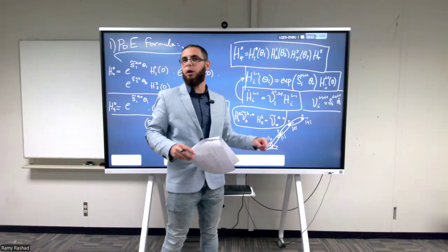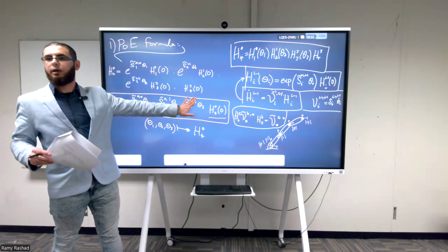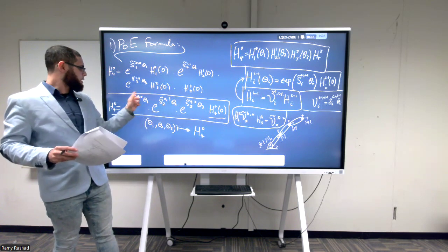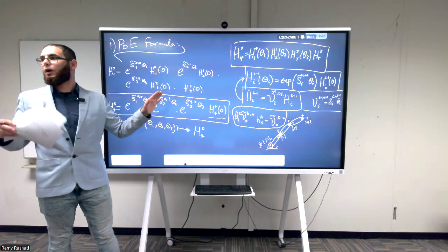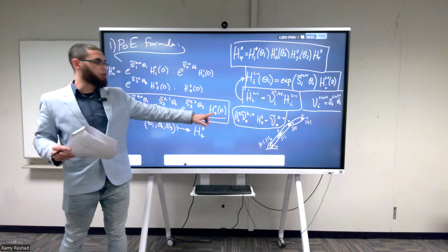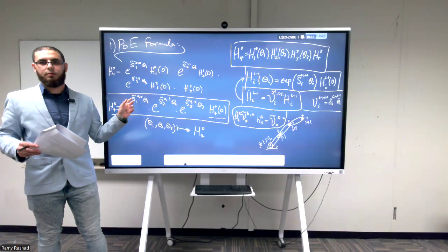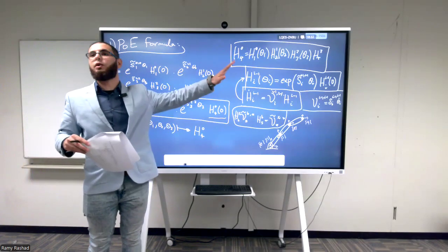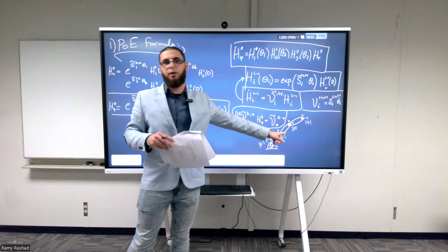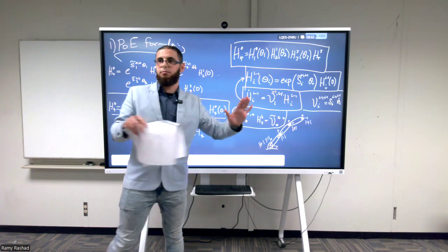What's more interesting is the 2, 1. So going from the 2, this one will drop out, okay? So I'm going to have H2, 0 multiplied by 2, 1, 0, and 1, 0, 0, everything with this part will be the same. If I want H1, 0 as a function of theta 1, theta 2 and theta 3, again, forget about these two, multiply H1 of 0 by this one, and it's very neat. So you can get all points you're interested in. If you have extra points in between, for example, center of mass frames, which we're going to do for the dynamics part, you can easily add frames, figure out what should be multiplied in this way, and it's a piece of cake.